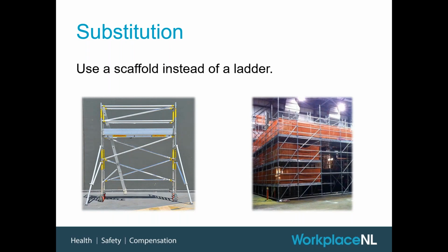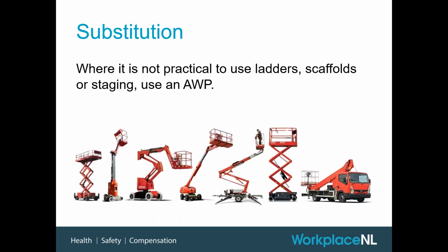Scaffolds, if they're properly laid out, may include some ladder components, but again, they provide that work platform with guard railing that makes it such that the worker doesn't need to worry about balance or 3-point contact. Again, they can be used with multiple workers, so there's a lot of benefits to avoiding using a ladder and using another system. But generally speaking, your scaffolding and your rolling platforms are going to be a little bit more expensive. So these are practical things to think about. But in some scenarios, this is just an easier way to go.